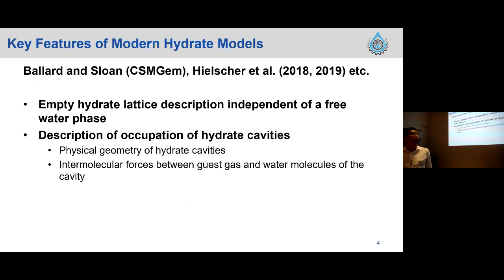So in terms of what a hydrate model consists of, the big breakthrough was with Ballard and Sloan in the implementation of CSM-GEM back in 2002, and the model I'm going to walk through today is based on this. And Hilscher built upon this model by improving the description of the empty hydrate lattice. So these are some of the namesakes in terms of hydrate model literature.